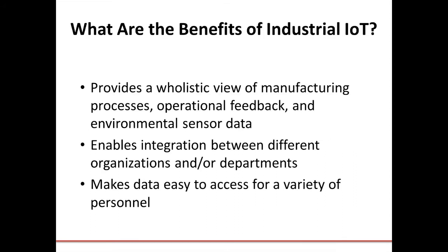So then what are the benefits of industrial IoT? Like I said, it's operating on the layer above SCADA to collect and present data. The goal of IIoT is to connect every machine in your factory onto one platform. The benefit is to go above and beyond things like start and stop status and production count. IIoT platforms provide enough storage space and processing power to collect metadata about your production processes, and that's where the real cost savings and benefits come in.